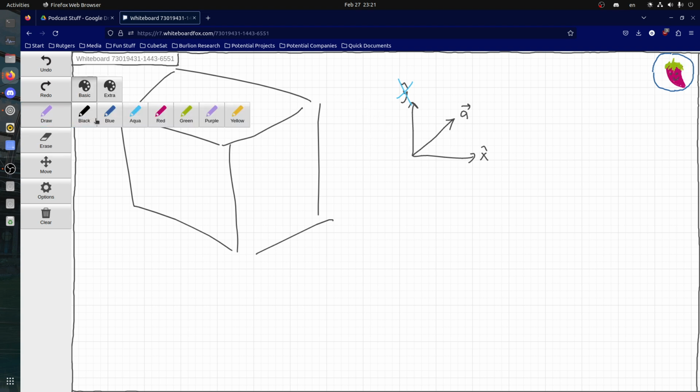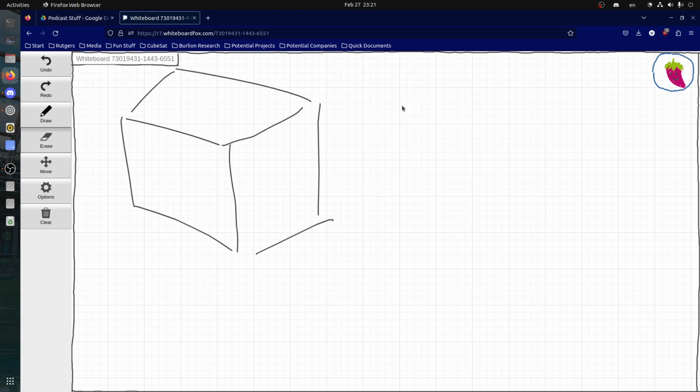So if you think of these axes as the axes about which you can rotate, then for a three-dimensional system, if you lose one reaction wheel, in this case the y, as long as the redundant reaction wheel is not perfectly parallel with these two, you'll still be able to rotate about any axes that you want. Yeah. So the reaction wheels are the first system.